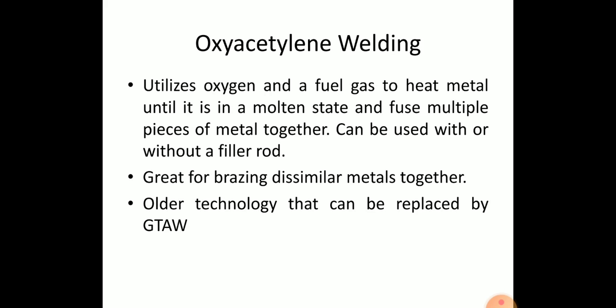The principle of oxyacetylene gas welding is that when acetylene mixes with oxygen in correct proportion in the welding torch and is ignited, a flame is produced which is sufficiently hot to melt and join the parent metal. Temperature of flame is about 3100 degrees Celsius. A filler rod is generally added to build up a seam for greater strength.